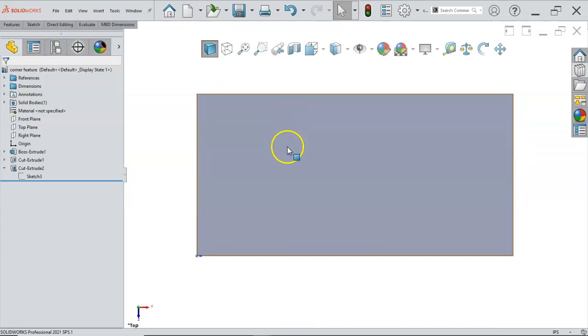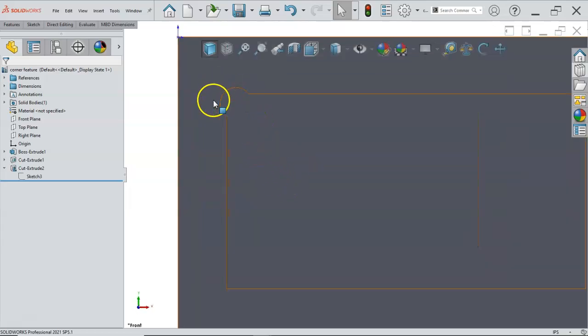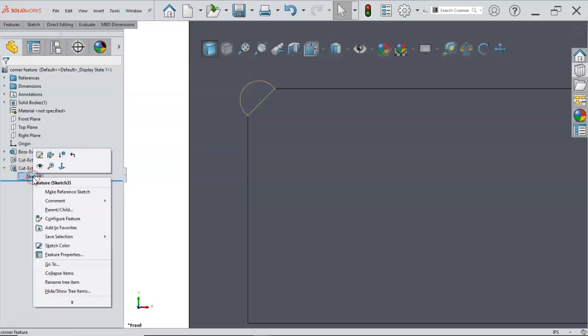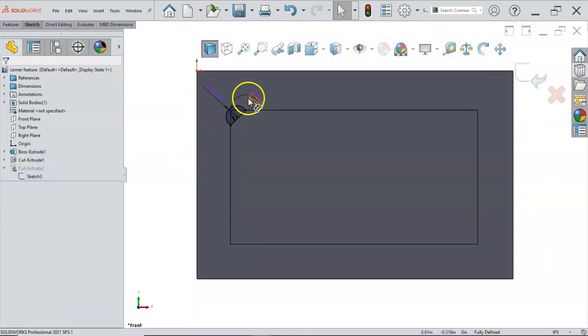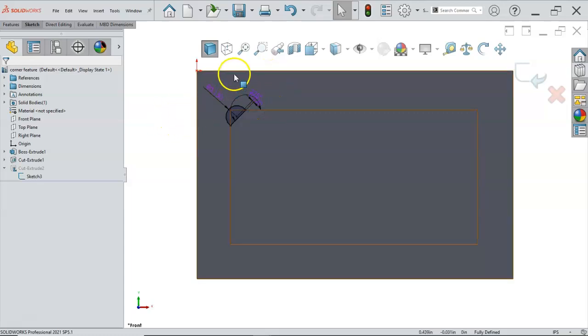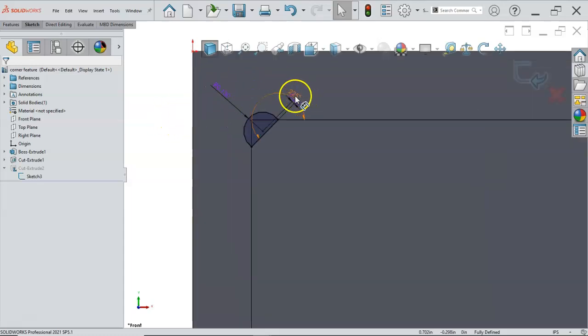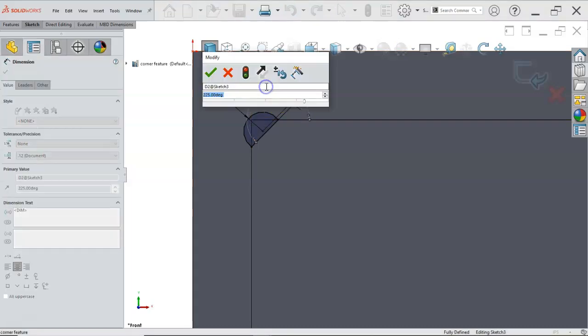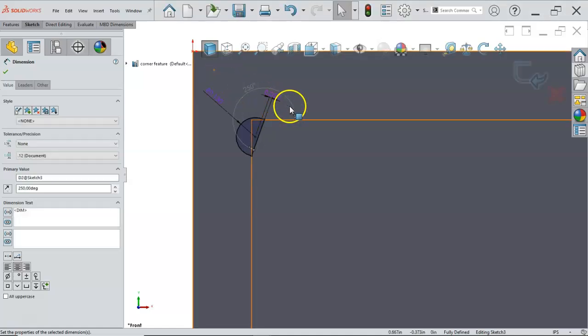And another quick advantage of using this kind of corner treatment is, if I was really close to the edge, maybe this geometry, I don't have a lot of room, I can play with this angle, and maybe we go to 270 is going to make it vertical, so not quite that much. 250, I can shift that over, and I can reduce that, and I will still have the same kind of relief at the corner, even though it overruns a little deeper.